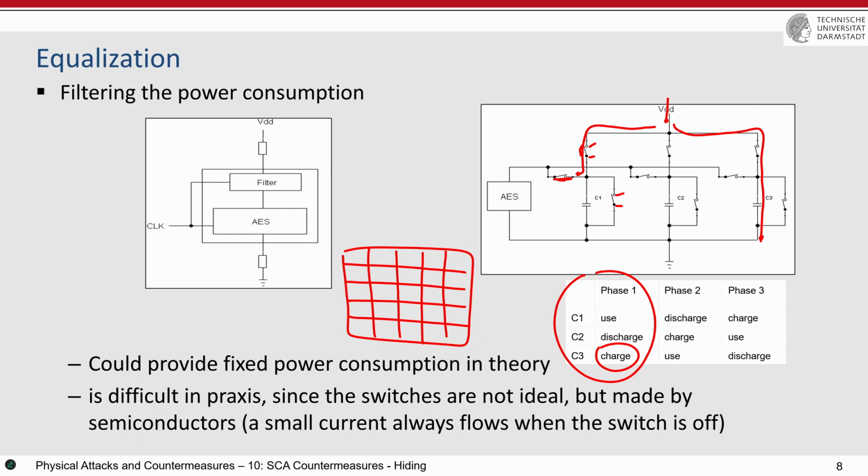And say that each tile, which has, let's say, 100 transistors, 100 gates, they have their own capacitors. They have their own C1, C2, C3, and also the charging and discharging facilities, each of them individually. One more thing which is important, the clock of these phases, phase 1, phase 2, and phase 3, should be completely independent of the clock of the AES. No, there shouldn't be any relation between them. Otherwise, you will be able to observe the signals more easily.